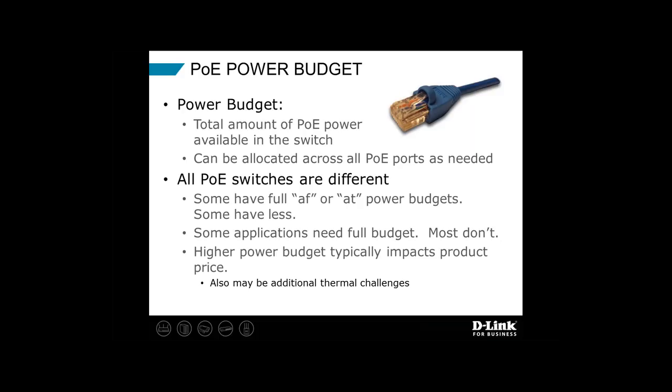Remember that all applications don't need a full budget. Most IP cameras, for example, I'm running an 8-port switch at home, and I have 8 IP cameras, and each camera is drawing between 2 to 6 watts. So I don't really need a lot of PoE budget in my switch. On the other hand, I do recognize that there are some wireless access points that support the new standard, 802.11 AC, and those do need a significant amount of power. And so if you've got an 8-port switch and you're powering 8 access points, you may need an 8-port switch with a higher budget.